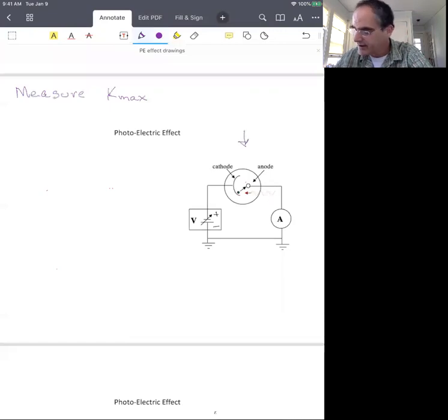Look carefully. First, we have a phototube which contains the cathode, the photocathode, in a glass envelope. It also contains an anode. So when electrons are excited from the photocathode, if they reach the anode, that'll correspond to an electric current flowing from cathode to anode, or electrons, cathode to anode.